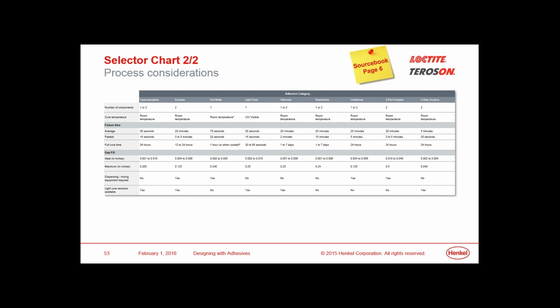In addition to the performance considerations, we want to talk about process considerations. Mike had mentioned earlier that one of the limitations of adhesives compared to mechanical techniques is that they must cure. They're not instantaneous. Even our instant adhesives require a certain number of seconds before they have cured. In addition, many adhesives have a certain amount of time that's required to reach what we call fixture cure, enough